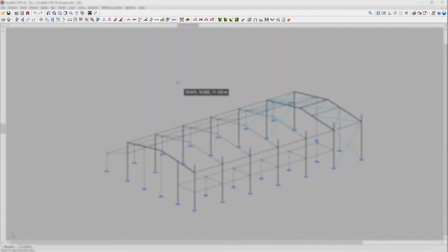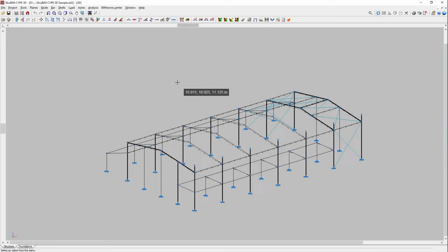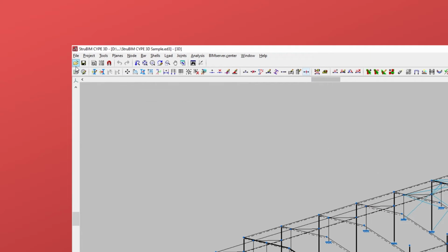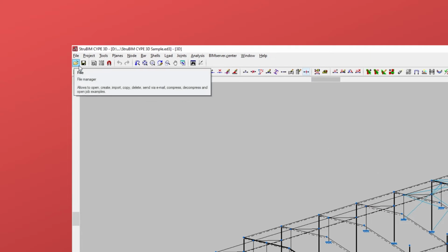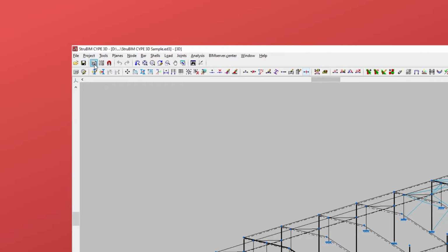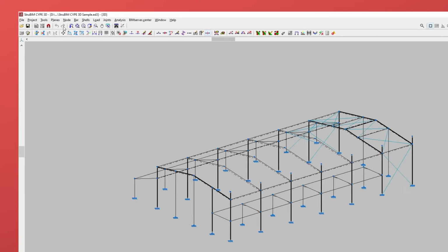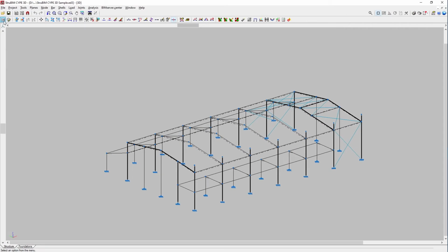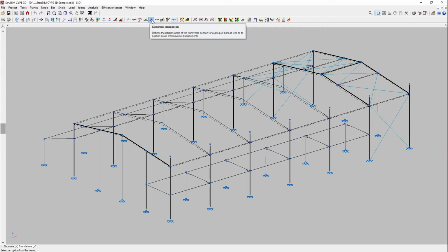Underneath the menu bar, there are two toolbars. On the left-hand side is the top toolbar to save, edit templates, edit views, the option to activate or deactivate references to elements in the job with template object snaps, as well as undo or redo the last actions carried out in the project. On the right-hand side of the toolbar, we have the options for printing reports and drawings, among others. The second toolbar includes buttons for the most important menu options, and it can be configured to suit our preferences.